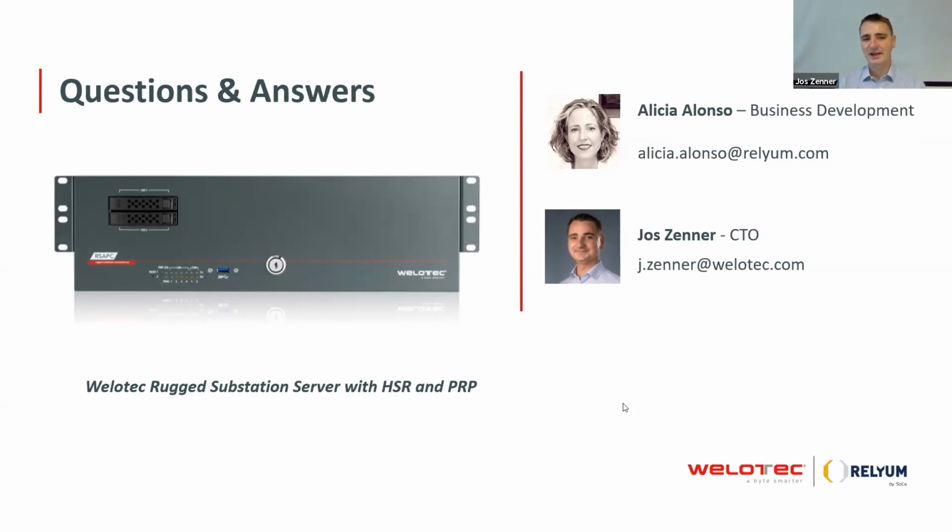A typical application is that you are running a substation gateway and the HMI on it as two virtual machines. And if you want, you can also add a firewall on it or an engineering workstation. So based on the demand of the single virtual machine, you can run 4 to 5 or maybe 6 different applications on one server. This is on the station bus where you don't have hard real-time requirements.